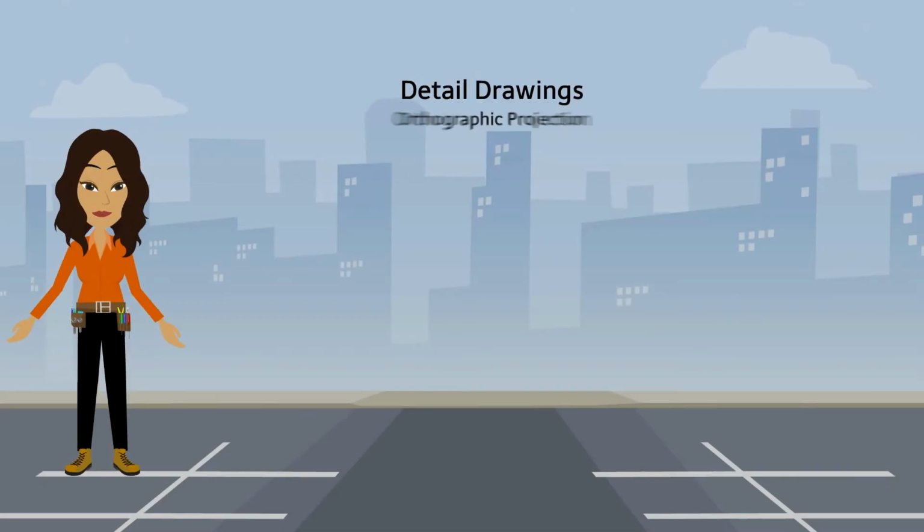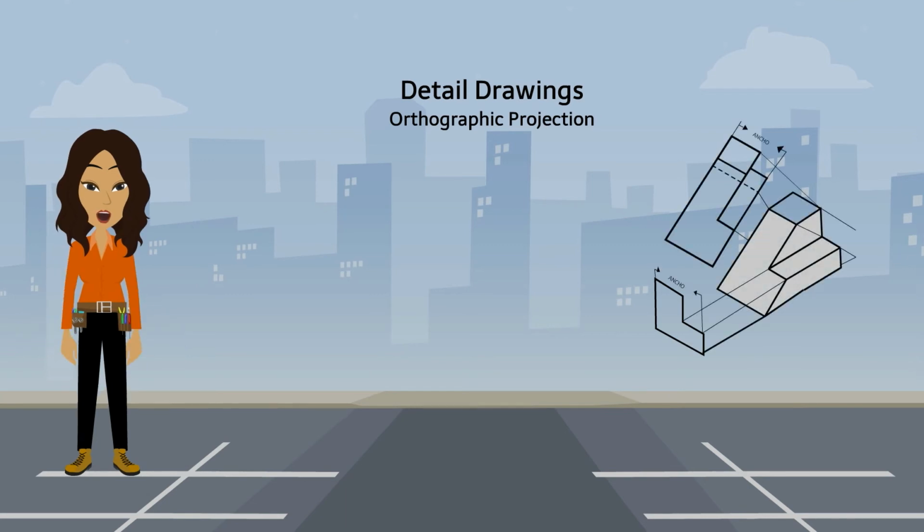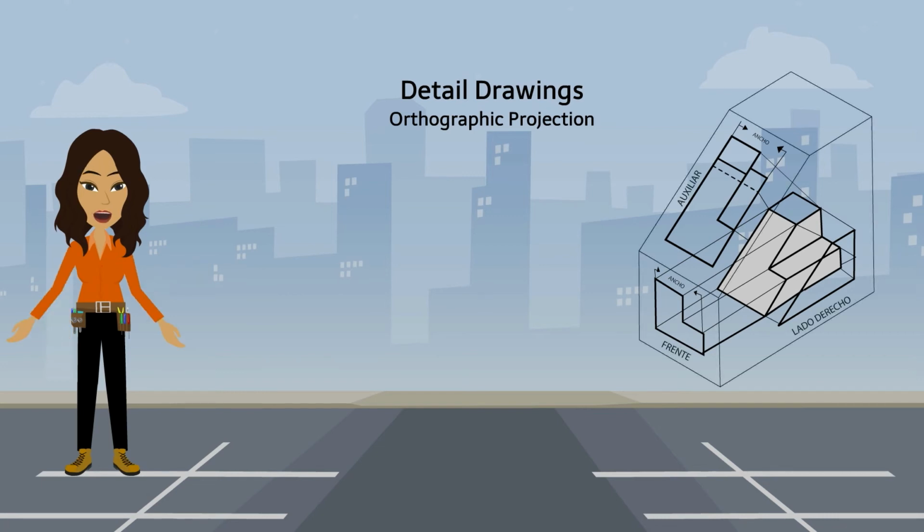Detailed drawings. Orthographic projection. Another term for detailed drawings is orthographic projection. Here, the object is drawn as a series of drawings, each two-dimensional and showing one surface. By combining two or more of these surface drawings, you will build a visual image of what the three-dimensional shape of the object is actually like. Generally, the front, top, and side views will be enough to show the shape of the object. However, you can use as many views as required.